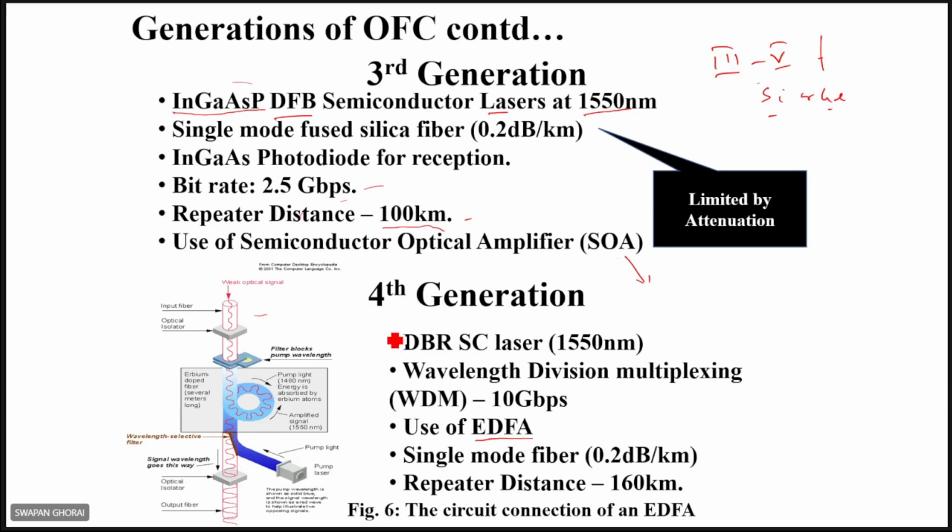Here, this figure you can see it here. Several components: input fibers, isolators, pump wavelengths. This shows how a fiber amplifier is used. In fact, you need some pump lasers. Here you see the pump laser. A portion of fiber is used for the amplifier. It is shown here. So suppose the signal is here, say a 1550 nanometer signal. You need to amplify these signals.